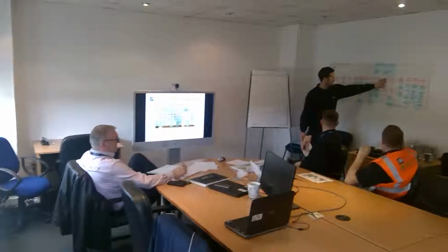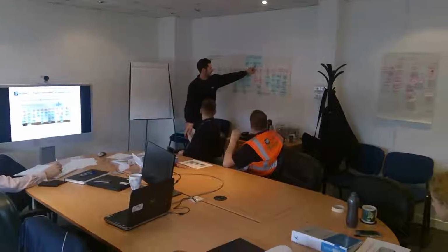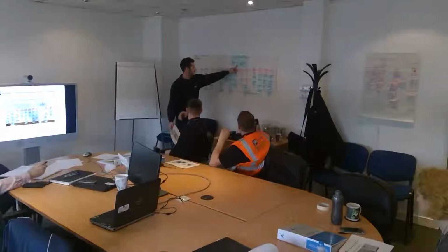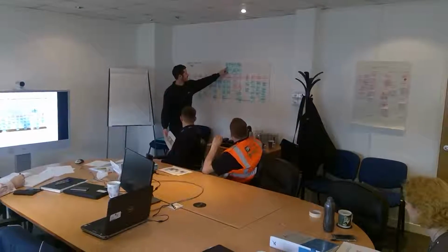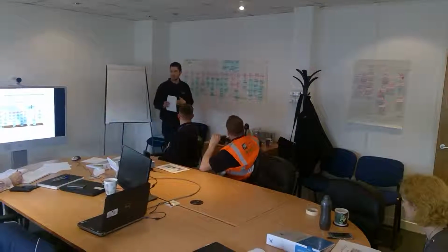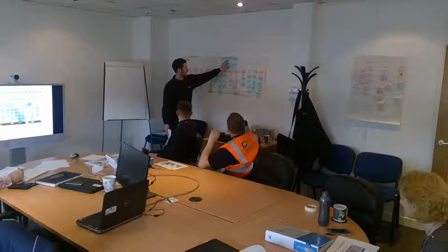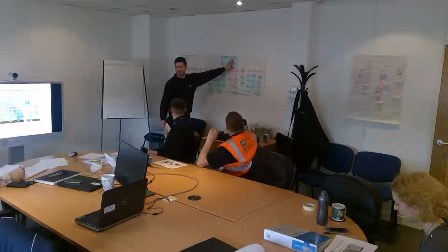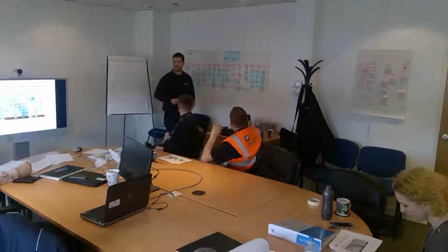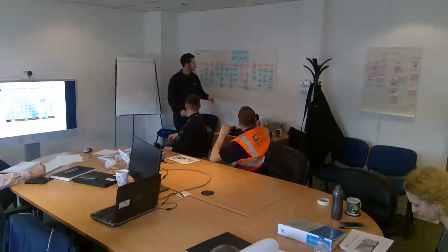From that we have a lot of problems we can have: human error, lack of equipment and materials, PPE issues, lack of welders and labour if we're short on men, pulled out of line, so things pull obviously when they're welded, they can distort and stuff like that. Welders not qualified to that procedure, again run out of gas, no welding procedure in place, so that could have been missed at handover stage, that we haven't got welders qualified to do this actual work.